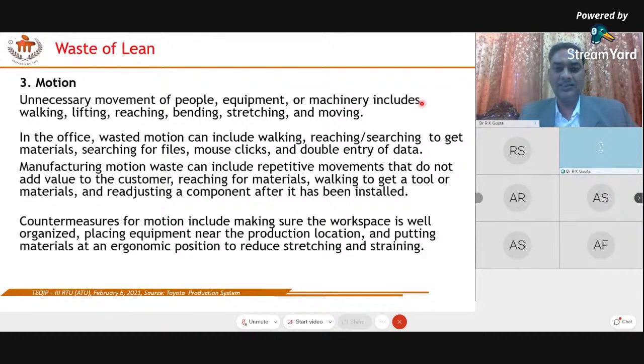And immediately after picking the bolt and the washer, the washer is put over the bolt, and the left hand is idle, and then the right hand does not move towards the body, it moves to where the nut is lying, searches for the nut, and then does the assembly. With this step-by-step process, we can reduce the time. Ultimately, we have reduced the time by a fraction of a second. But if we do this for 8 hours, or for 1 week or a month, and you calculate the time, it drastically reduces the time and saves the amount.